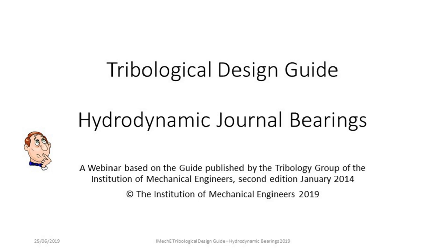Okay, but do we find in practical applications that people design beyond 4 megapascal? Well, not when we're talking about full film fluid bearings.